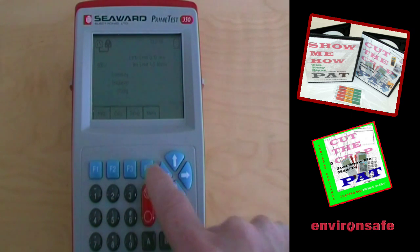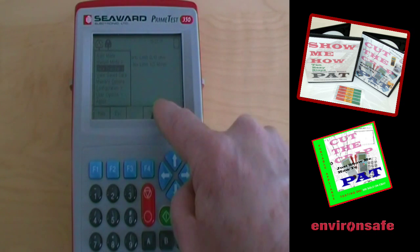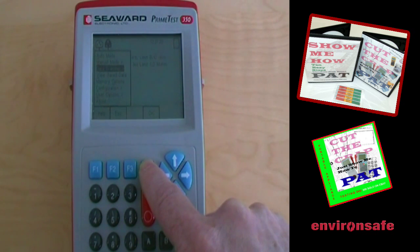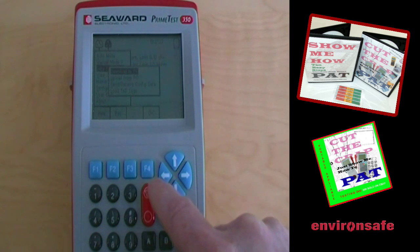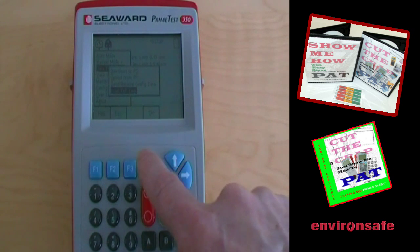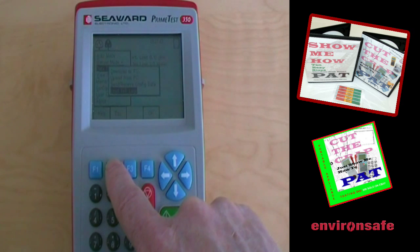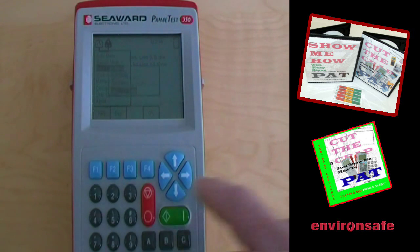F4 for the main menu, using the direction arrow keys to data transfer. F4 OK, and the choices we have here are to download to a PC, upload from a PC, send and receive configuration data, and load test and tag logo. If you wanted to choose one of these, you would press OK, F4. We're going to escape by pressing F2.